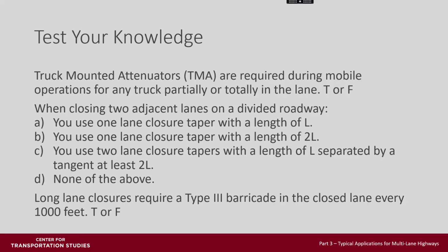Let's take a moment to talk about what we've just talked about here. Truck mounted attenuators are required during mobile operations for any truck partially or totally in the lane. That is false. If you remember, they are recommended, they are not required.